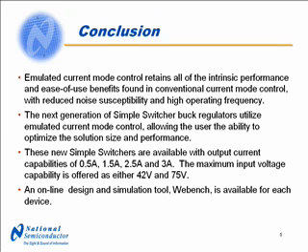These next generation simple switchers are available with output current capabilities of 0.5 amps, 1.5 amps, 2.5 amps, and 3 amps. The maximum input voltage capability is offered as either 42 volts or 75 volts. An online design and simulation tool, WEBENCH, is available for each device.